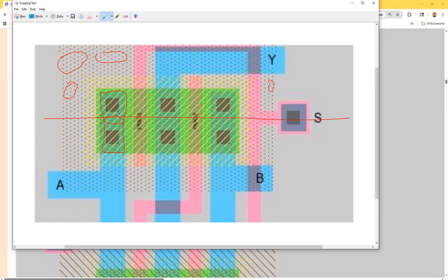So whenever the P select and P plus are done, you put the insulation layer and the poly, and you will never be able to do anything else with the bottom anymore. It's done. It's covered. Yeah. So start doing metal 1, metal 2. Okay.